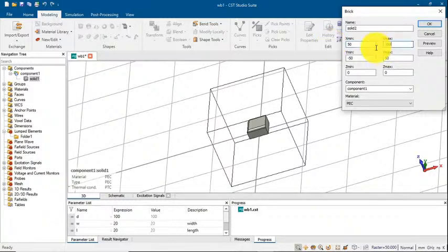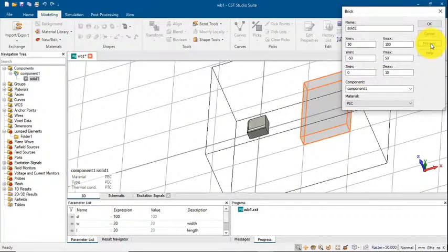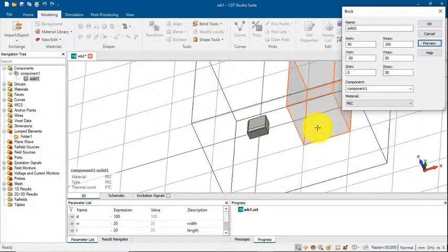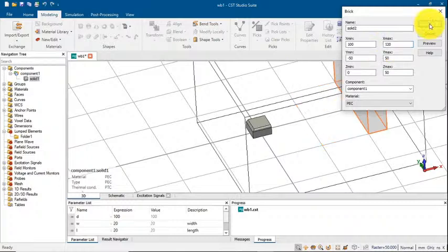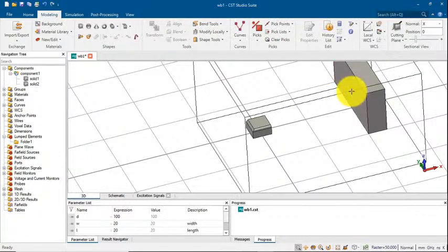I will tell you because I want to change the position from 0 to here, because I want to use a new technique, okay? And for Y, -50 to 50, it's not a big problem. For Z will be 10. Let me press preview. Okay, instead of 10, let me take it to 50. Preview. Okay, that's great. But instead of 50, let me add 100, and this will be 120. Preview. Okay, that's great. So we have another object at this.